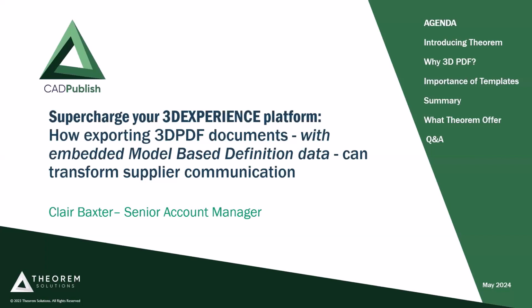So this webinar will focus on our complementary tool that integrates directly into the 3DEXPERIENCE platform. The technology we'll be showing today allows 3DEXPERIENCE users to export directly into the rich 3D PDF format. So we'll show some examples of how you can export directly within the system, but with all of that MBD information, all of that model-based definition data included. So the PMI, GD&T, FTA, it's known under many different names and guises, but you'll see how that is all carried through into the PDF.